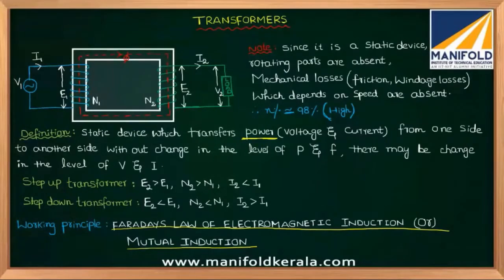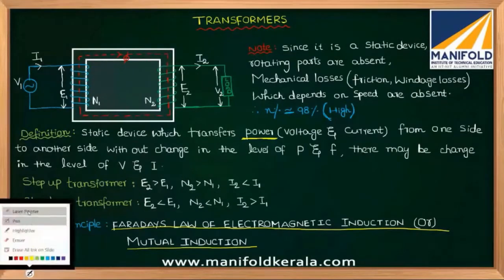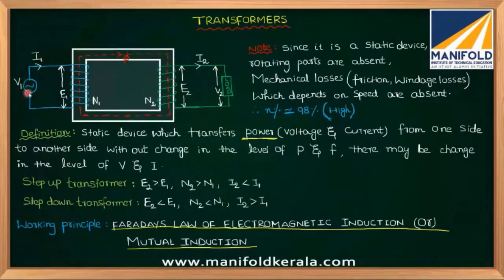Now tell me the reason why a transformer can be called a single excited device. Very simple. One supply. Very good, Vishnu. I am giving only one source. I connected only one external voltage source, a time variant voltage source. Because of this, it will take some current, which is a time varying current. Because of the time varying current, some flux will be produced in the transformer core.